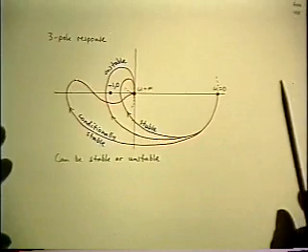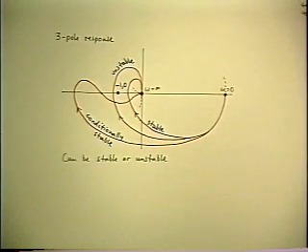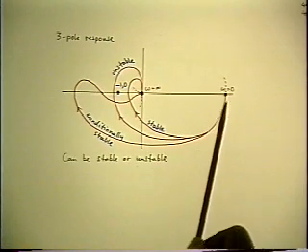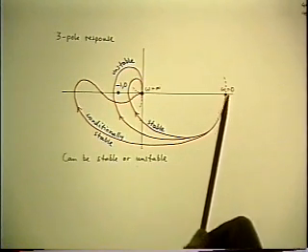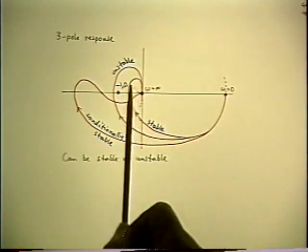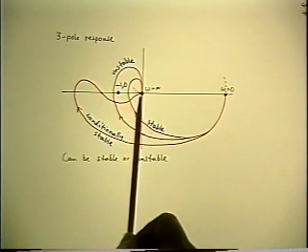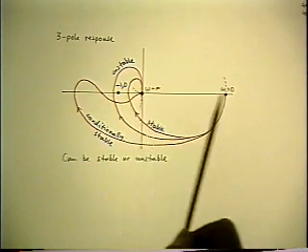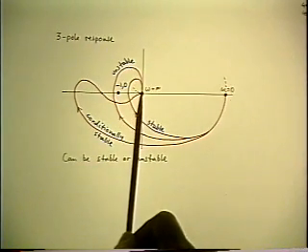It's when you get to three poles and up that you have possible problems. Take the smallest of these contours. This is three poles now, because you end up at infinite frequency with zero magnitude, but from the 270 degree direction, 90 degrees from each of the three poles.